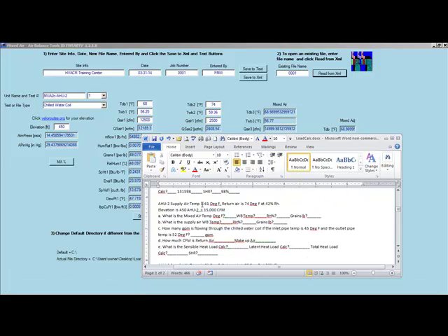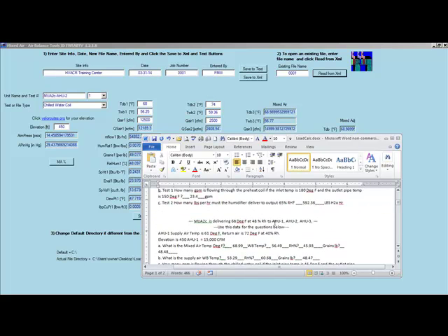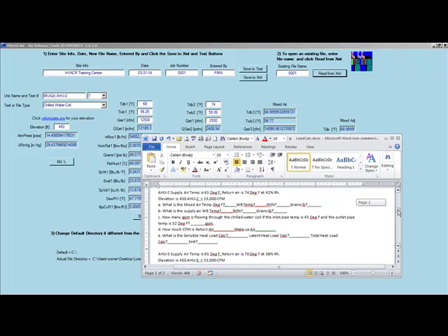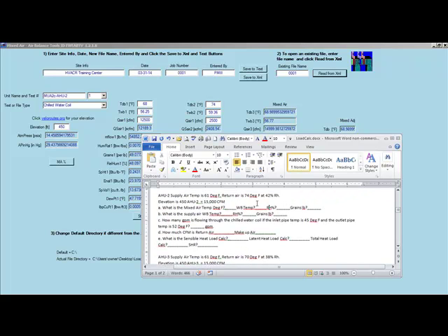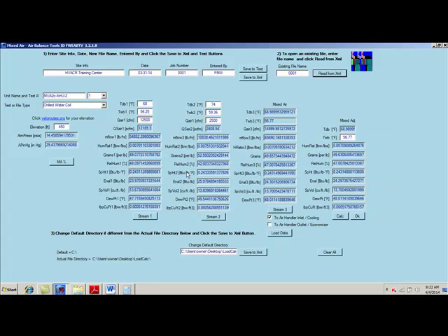It's saying that our supplier, by the way, our makeup air unit is still the same, 68/48. So let's take a look at the mixed air for air handler number 2. Our return air is 74/42. So 74, 42, 68, 48. Okay, so we have all our values in. And again, we have 68.9, or in this case, we would say 69.